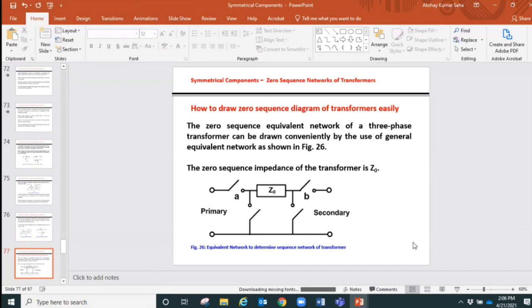And the zero sequence impedance of the synchronous machine depends on two things. First, the zero sequence impedance of the machine winding. Second, the type of grounding. Are we grounding the neutral solidly, or leaving it open, or grounding via some impedance, via some transformer? What is the value or the range of the impedance? So that's for the synchronous machine, a rotating device.